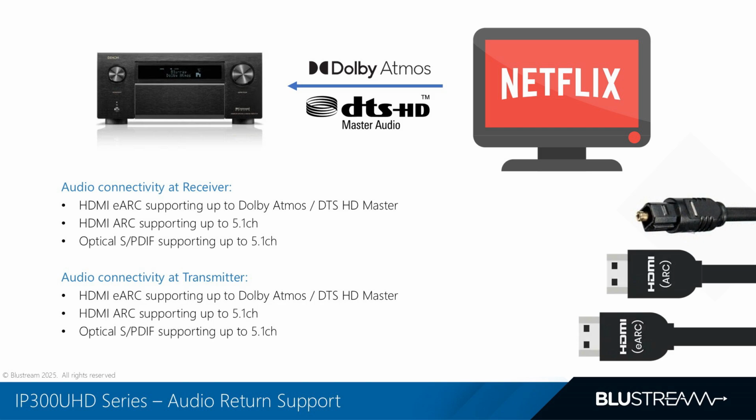This return audio can be routed back to a fixed transmitter at the head end, either to an HDMI input on an AVR processor or broken out via optical for connection to other equipment. And with eARC, you'll get full support for today's highest quality formats, including Dolby Atmos, DTS:X, and DTS-HD Master Audio, all sent back over the network with no compromise in quality.